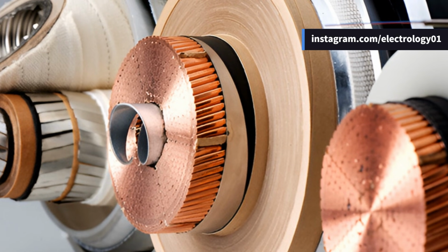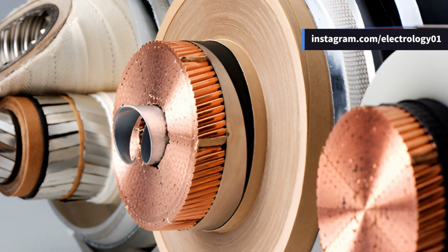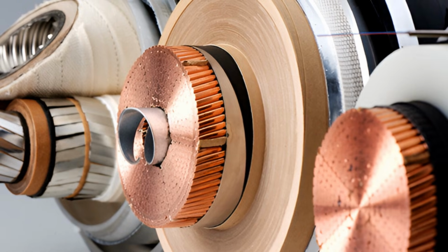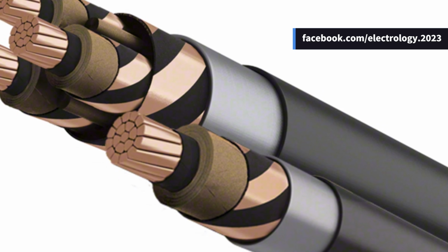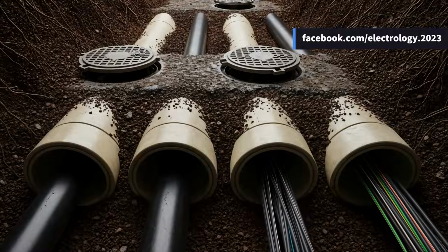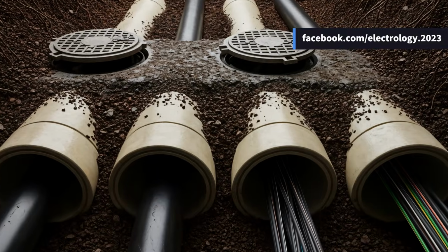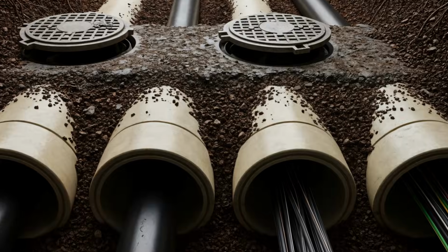And just like how your body has a limit for how much heat it can tolerate, cables also have a maximum permissible temperature rise that governs how much current they can safely carry. This temperature rise occurs because of the various losses inside the cable. Copper losses in the conductor, hysteresis losses in the dielectric, and eddy current losses in the sheath. All of these combine to generate heat.